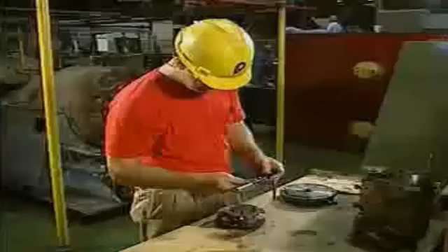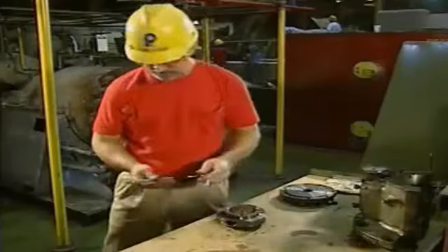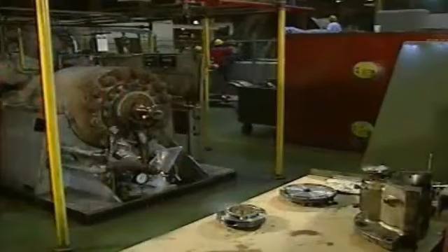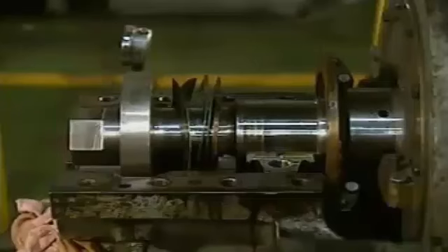To obtain the total clearance, the mechanic subtracts the diameter of the shaft from the inside diameter of the bearing. If the total clearance is too great, the bearing inserts are replaced and the test is repeated. If there is too little clearance, the bearing is either replaced with a bearing of the correct size or else it is scraped down. After the clearance check is made, the journal bearing is ready for reassembly.